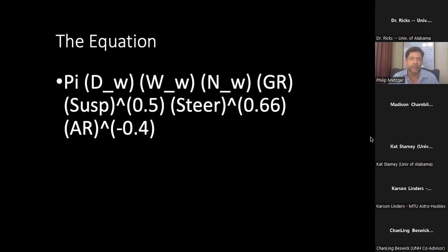But then there's another issue. We have seen teams make the mistake of not fully retracting their digging system because it's a timed event. They're in a hurry. They start to retract it, but before it's fully retracted, they try to drive forward. And that causes one of these initiating events to occur. Your digging mechanism hits the ground, your wheels slip, and once the wheels slip, they start to shear the soil and fluff it, and then you have a chain reaction, and then they get stuck. So I guess that's about all I can say about the interaction between the mining and the mobility at this point.